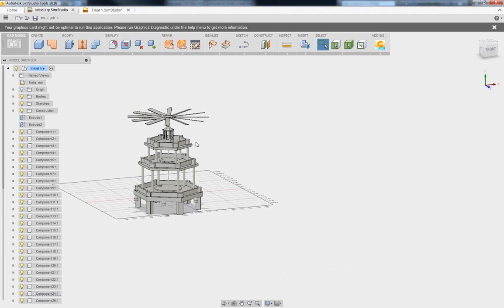Then I started to run into errors with my rotating region peripheral nodes, and solver exiting unexpectedly before I could get to iteration 1. So I had to do some cleanup on my rotating region, and from there, I finally got to start iterating, and I got to figure out my time step size, because, yeah, I chose something that was too big to begin with and diverged. I chose something that was too small, and I couldn't really get it to ramp up in a reasonable amount of time. You know, I don't want this to run for 2 weeks. I need something with a faster turnaround. So I ran into those problems.